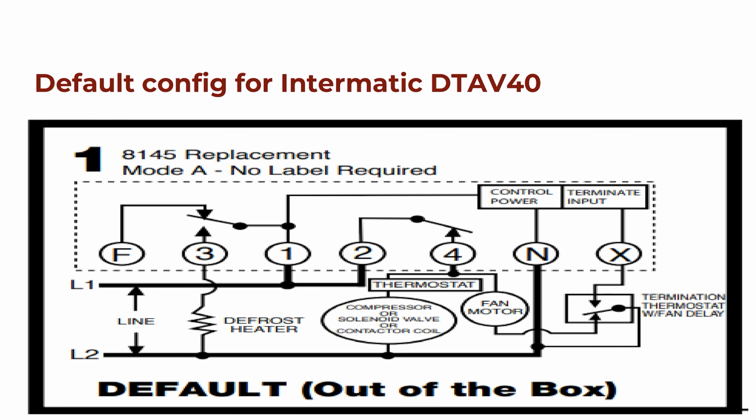If we're trying to figure out why this fan motor isn't running, and we have this thermostat in the system, it's like, okay, we don't have defrost on. There's no power to defrost. We're not in defrost mode. My fan's not running. What would I do to figure that out? Okay, test power at the fan. Okay, there's no power at the fan. If there was power at the fan and the fan wasn't running, I could probably conclude that the fan is bad. But there's no power.